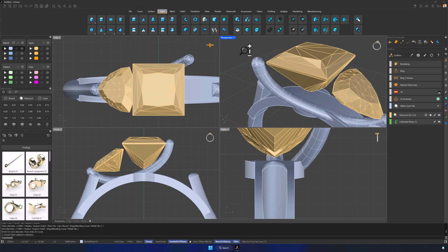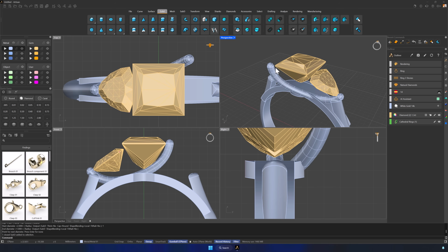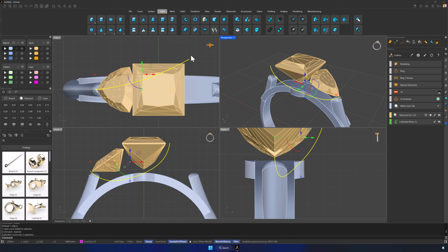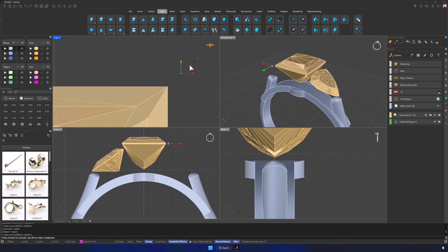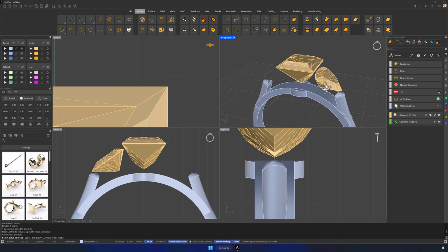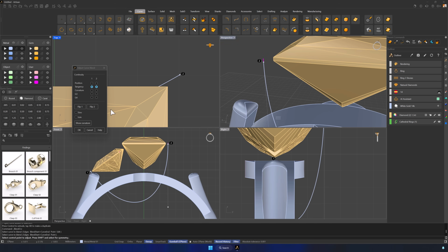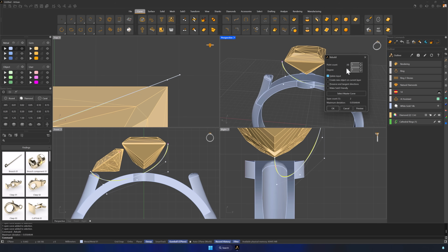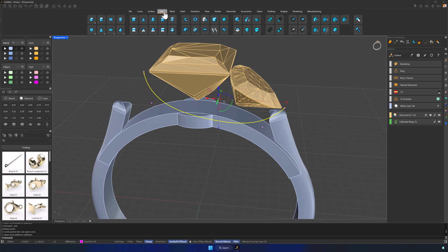If it looks too far from the gem, it means one of the edges was moved too far. To fix this, select the joined curve and explode it to separate the parts. Delete the blended curve and reposition the edge closer to the gem. Then, blend again with tangent continuity, adjust the control points, rebuild with 5 points, and repeat the previous adjustments. Join them again and create another pipe of 1 mm. Now the prong properly holds the gem.